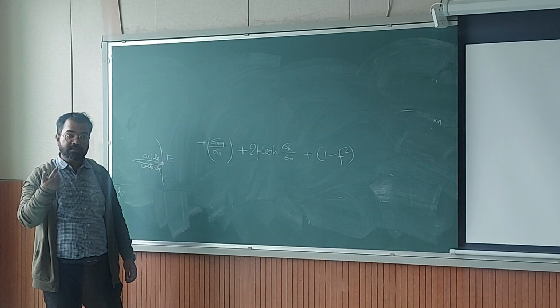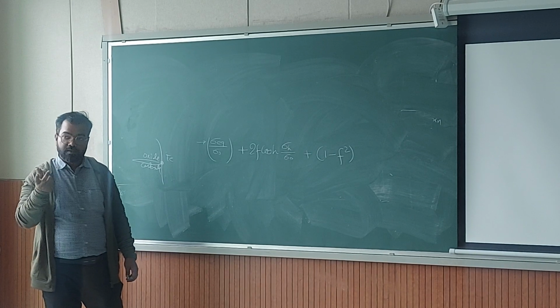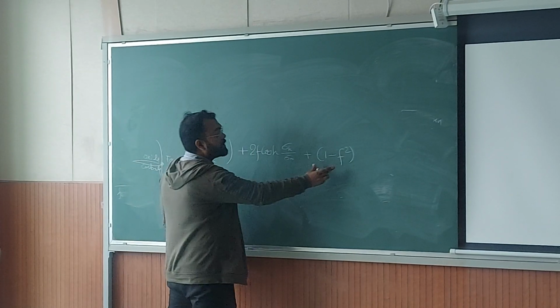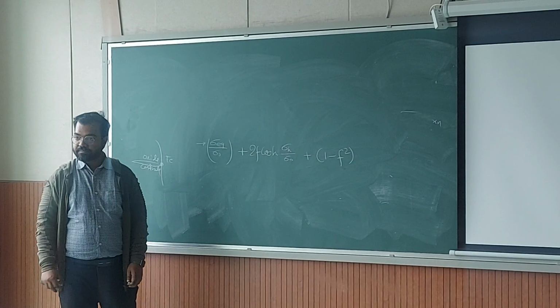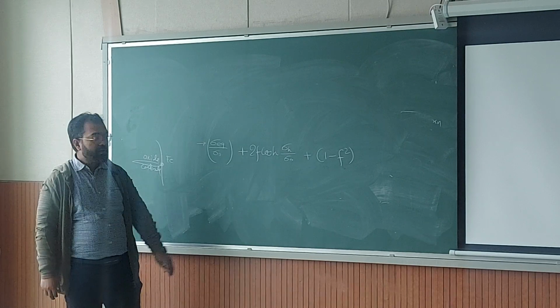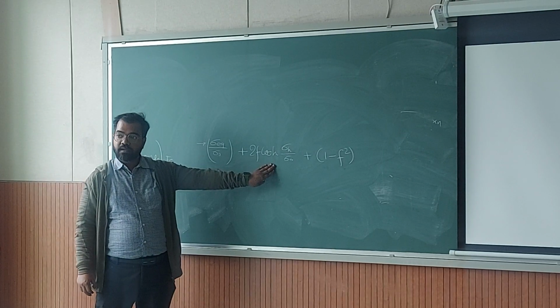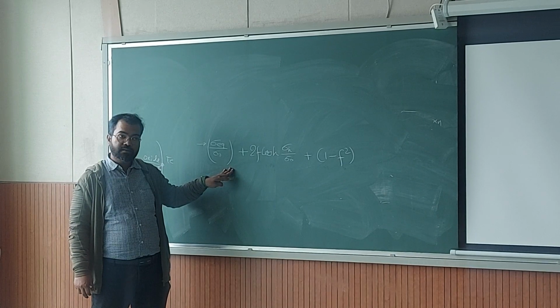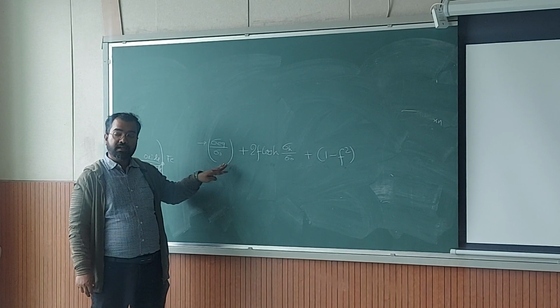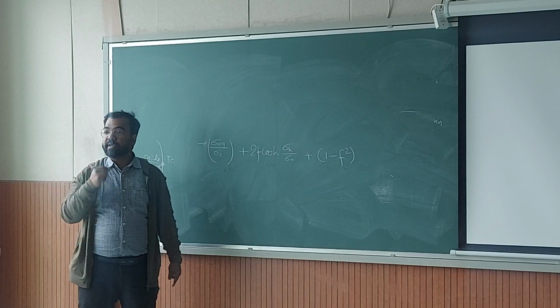Is it making any sense? Okay, so I must take care of how much void volume fraction is forming in every step, how much growth is happening, how much nucleation of void is happening. Okay, so this will be defining my new yield point.